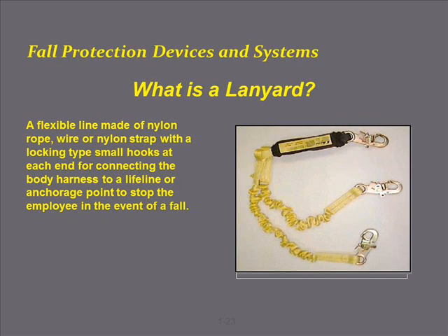What is a lanyard? A lanyard is a flexible line made of nylon rope, wire, or nylon strap with locking type, small hooks at each end for connecting the full body harness to a lifeline or anchorage point to stop the employee in the event of a fall.